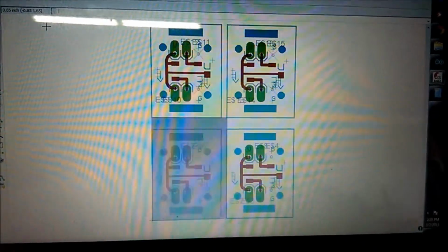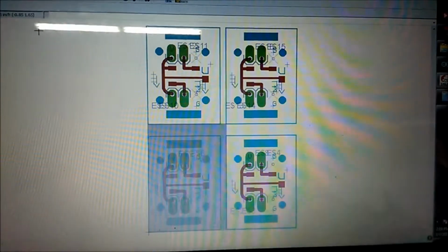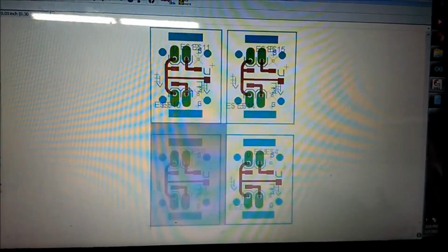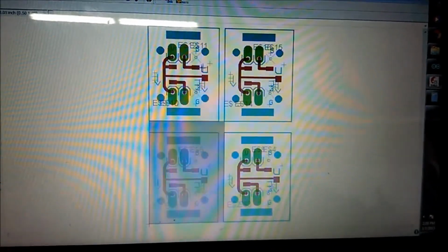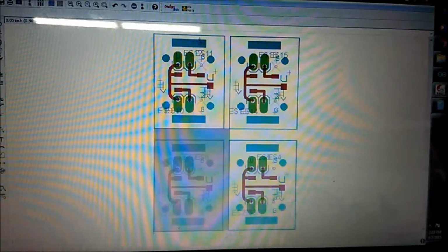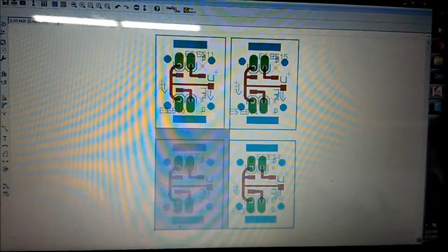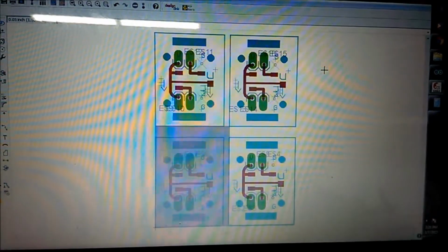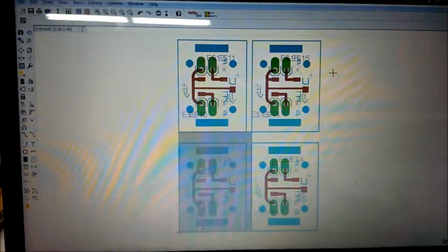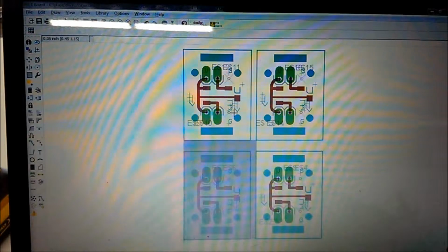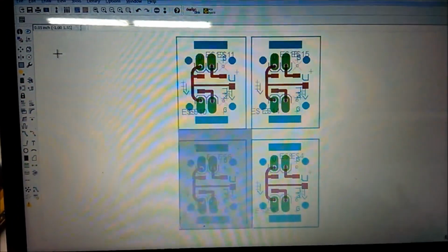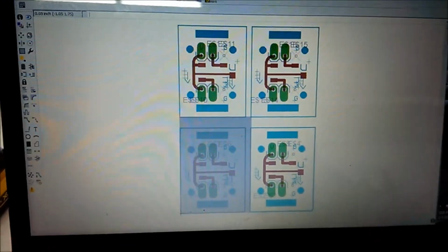And that's the toolpath. Okay, so now we have our toolpath generated for the CNC mill for outlining the traces, doing our hole drills, and also doing some of this reference text on it. Like I said, I don't like doing the outside milling of the board, which would be the final cut all the way through, because this plug-in will only do a single pass. It's really tough on the machine, and I haven't had much luck without going really slow. So I have a better program for that.